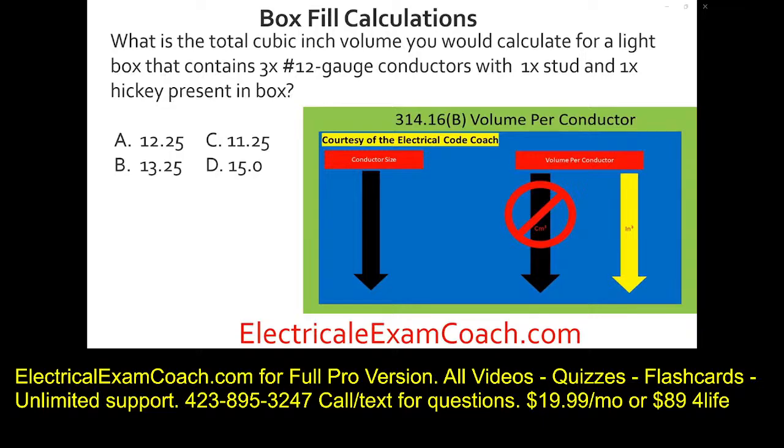What is the total cubic inch volume you would calculate for a light box that contains 3 12-gauge conductors with 1 stud and 1 hickey present in the box? For this one, we're going to go to table 314.16(B). We know that each 12 is 2.25 cubic inches. Now let's count our conductors. We know that we have the three number 12s originally, but now we have to deal with the studs and the hickeys.